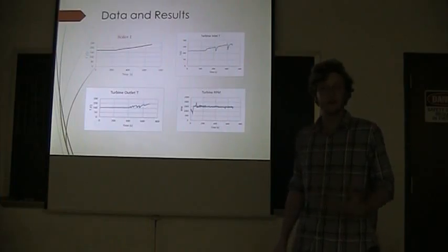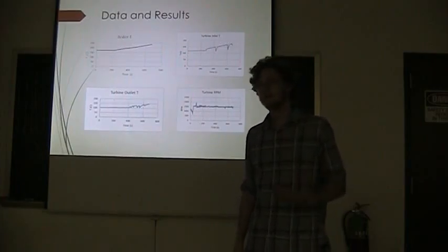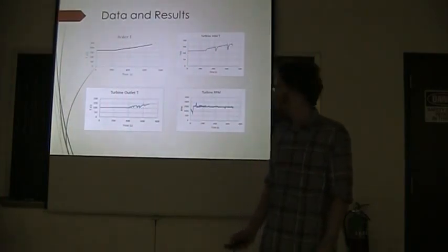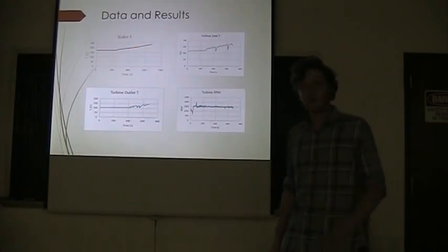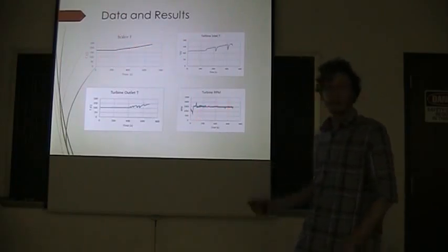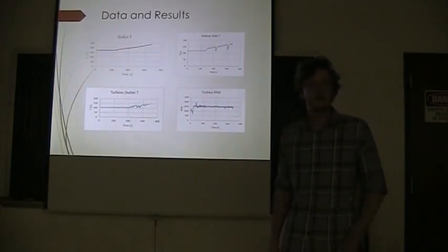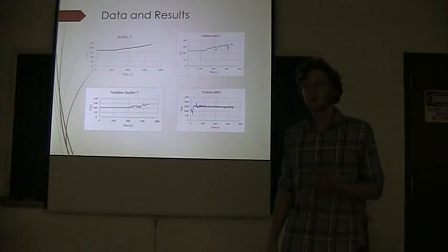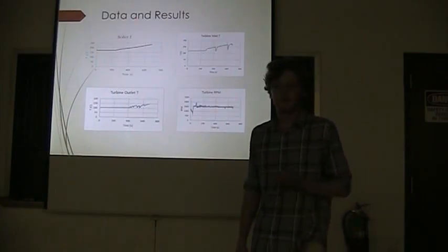It's not designed to do this, and it's actually going to decrease the efficiency, which is shown by that if we increase the heat that we're using from the boiler right here, which is our input from burning the liquid propane, the RPMs of the turbine should increase, and they don't because it's only set up to handle a certain speed anyways. So these are some notable dips before we even get into calculations to show some issues with our efficiency.